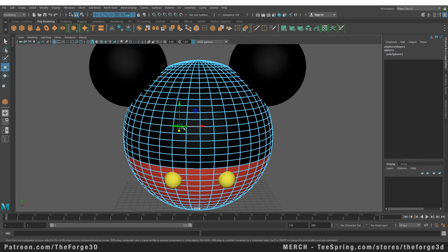this. Now if you want to select, for example, edges from here to here, you don't need to select them individually. You can just select your initial selection and double click on your last selection. That will select all the edges that you have in between. Or if you want to select the complete edge loop, which is this continuous line that revolves around the object, you just need to double click on this line and that will select the complete edge loop.